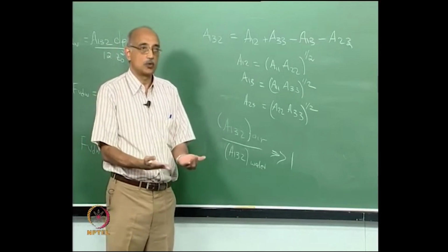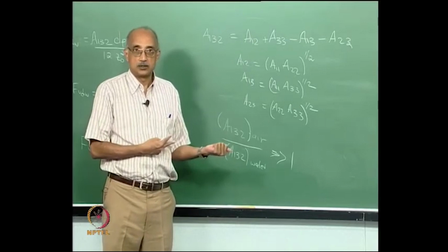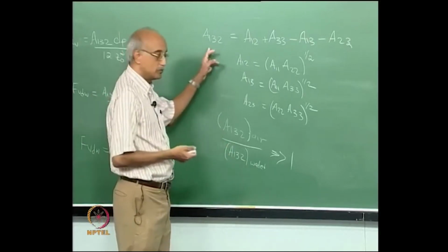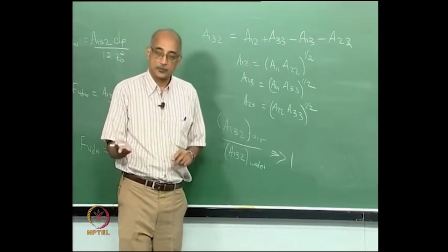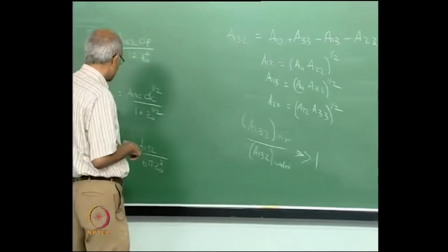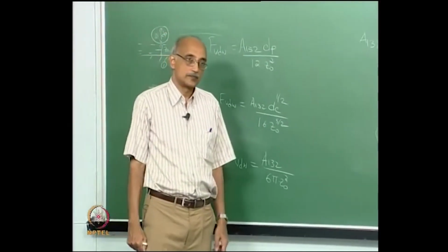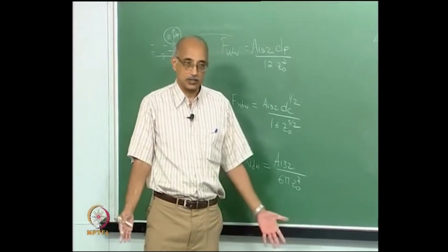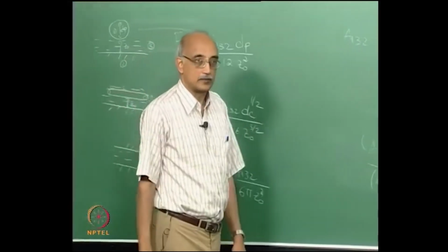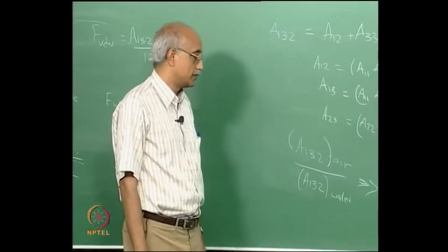As soon as you soak it in water, the Hamaker constant drops by an order of magnitude, by about 10 times. So the effective A132 also drops, not by 10 times, maybe by about 5 times, and because of that the van der Waals forces of adhesion also decrease significantly, and that is why wet washing is always easier to accomplish than dry cleaning. That is one important implication here.